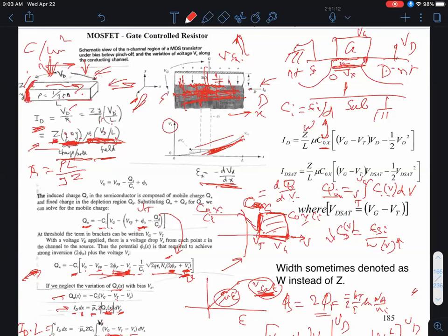All right, so now that I have that expression for the resistor, we looked at the MOSFET and tried to make the correspondence. We need some way of coming up with an expression for the sheet charge per unit area in the inversion region, okay? To do that, we looked at the capacitance voltage behavior. This is the overall gate capacitance C as a function of the gate voltage.